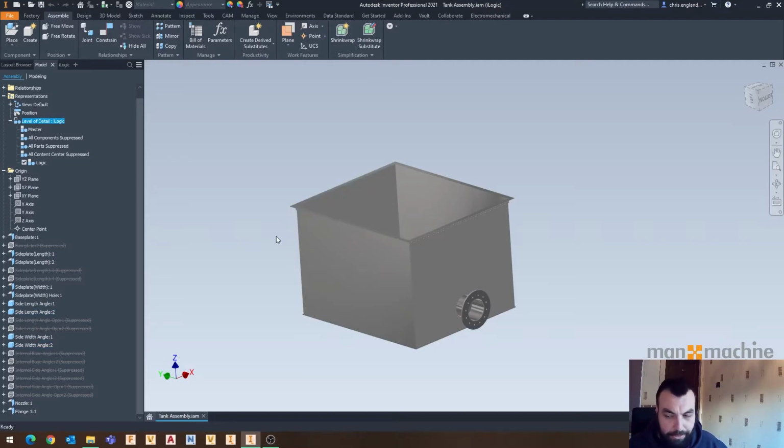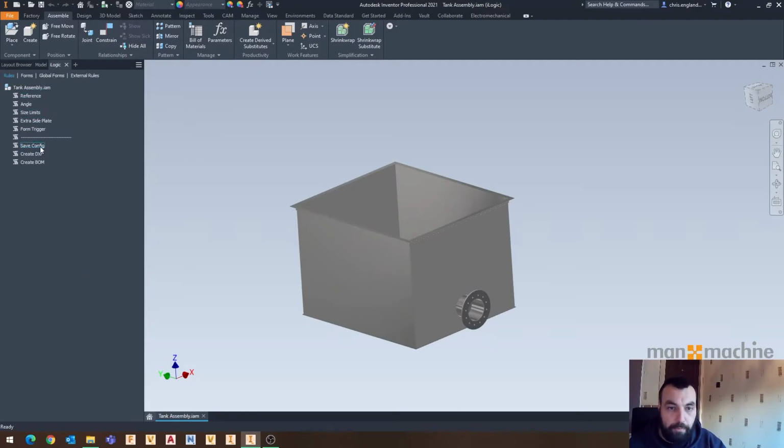It gets a bit trickier as you start stacking up the extra things that you're trying to do. Like I mentioned earlier on, with the bill of materials, if you got a standard or created a standard rule to just export the bill of materials, often enough the level of detail plays a bit of havoc there, which is why I use the method that I do, creating a drawing with a parts list and then using the rule to extract that parts list, which, by the way, I've left that rule for you.